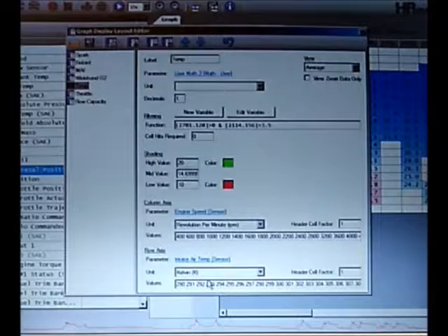If it's wintertime and it's minus 20 degrees outside, your intake temperature is usually warmer than the ambient temperature. It might reach something close to 0. If you want to be careful and cover everything, just pick a range that's safe, like minus 10 degrees Celsius up to, I don't know, 50 or 60 degrees Celsius, and add those numbers, minus 10 and 60, to 273 for the low and the high end.